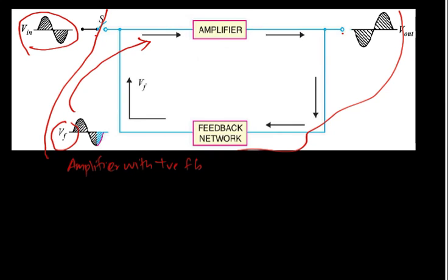A capacitor is charged by connecting to a battery or a DC source. So the electrostatic energy stored in the capacitor produces oscillation. That oscillation can be connected to the amplifier circuit, so the amplifier amplifies it, and a part of this output is fed back to the input, and this feedback network is again connected to the oscillatory circuit to meet the losses. So when we connect an oscillatory circuit here or a tank circuit here, then it will act as a perfect oscillator.